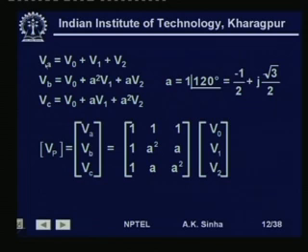So, writing this set of equations where we write A, B, C quantities as phase quantities. We write this as Vp, a set of phase voltages Va, Vb and Vc, equal to this matrix, which is 1 1 1 for this: 1 V0 plus 1 V1 plus 1 V2.